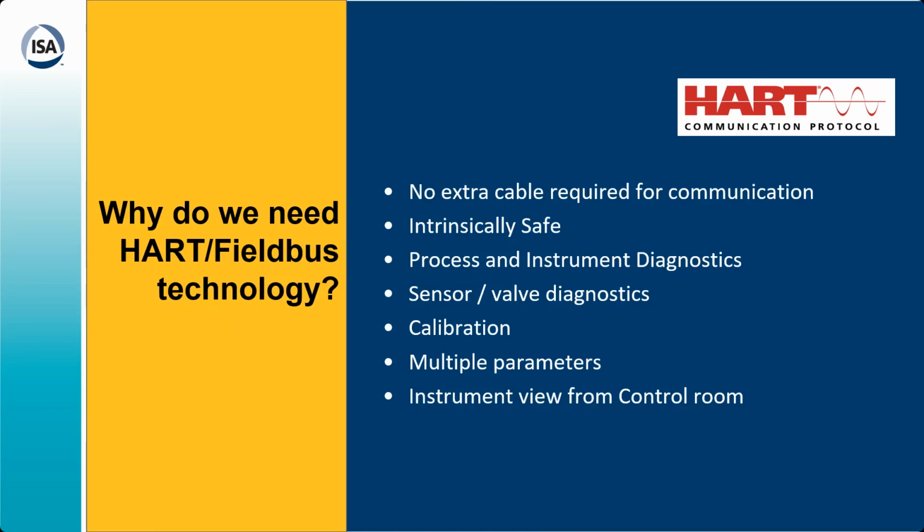So this is a technology which is normally available in the plant at no extra cost. That is one of the better advantages of this technology. For fieldbus you need a greenfield installation and separate cabling, but for HART that is not required. Wireless HART also can be used for predictive maintenance technologies. That's a very latest technology available, and you don't need cabling for that.